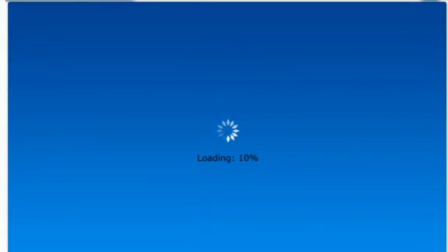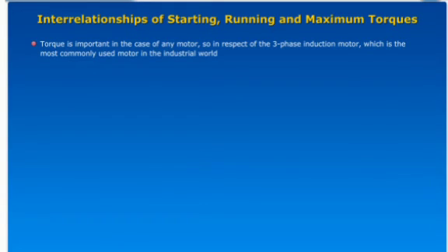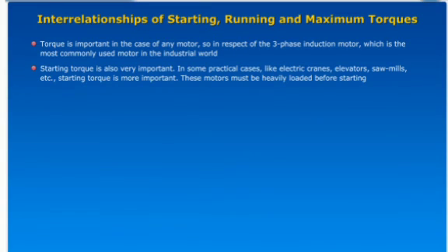Equivalent circuit of the rotor. The rotor may be represented by the following circuit. Dividing both the numerator and denominator with S, the resistance term R2 by S could be split into two parts. The first term R2 is rotor resistance. The second term represents an equivalent resistance. Pm equal to mechanical power developed.